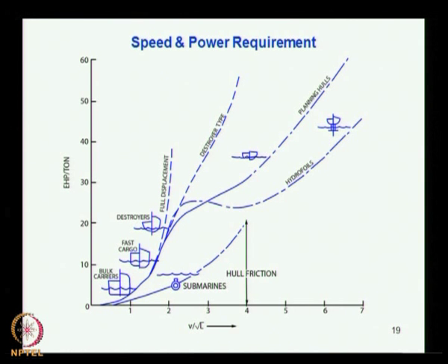And it is much better for the case of a hydrofoil craft. Hydrofoil crafts have a foil beneath the vessel, which when moving forward through water generates lift, and this lift puts the vessel up above the water. So the resistance comes down drastically, and due to that it can attain higher speed with the same power.